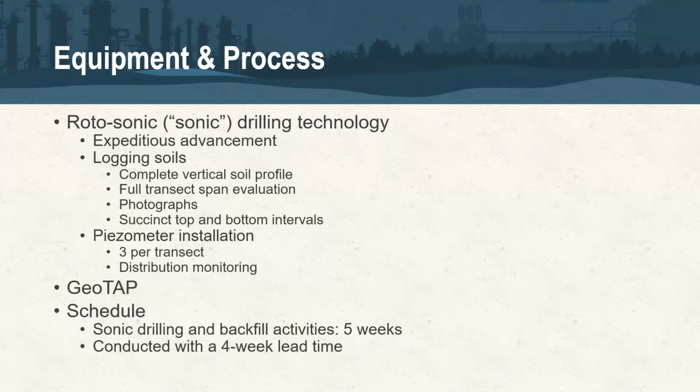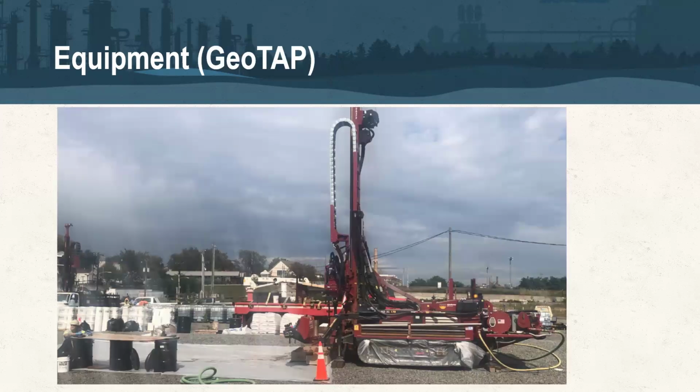But basically, this is a pre-drill access to the subsurface, right? We're creating a pathway for us to do DPT injection in a geological regime that would normally result in DPT refusal. So we pre-drilled each of our injection points here. In doing that, we had to start the sonic drilling well ahead of the injections because the injections happen so quickly, which we'll talk about in a second, that we would have caught up to our drilling crew if we had not done that.